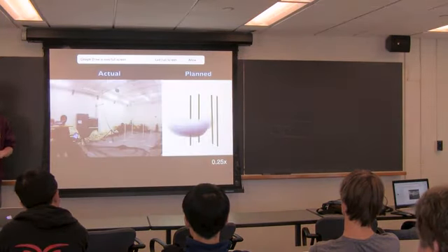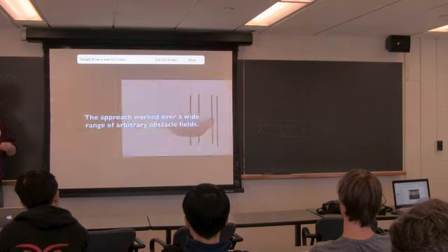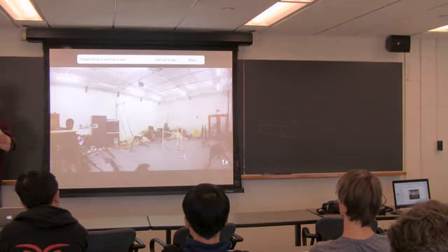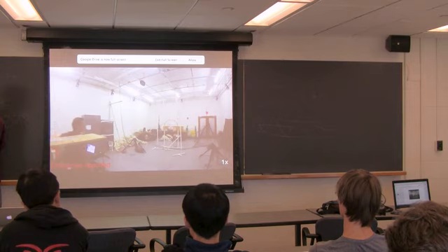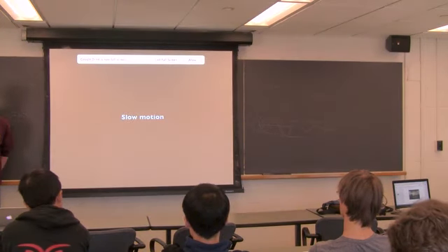So one way that it finds the best one is by finding all of, so if you're planning in a point cloud, you find all the points that lie within the ellipsoids, and the one with the least amount of points is probably going to be the safest one. So here's a bunch of different obstacles, and it safely maneuvers all of them. And there's some pretty dynamic movements, which is cool too.